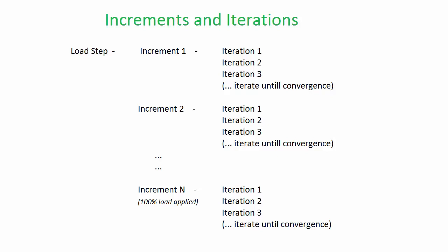However, in a nonlinear analysis, it is almost always better to set smaller increments. This is because the solver is unlikely to converge to the solution when it applies the entire load in one increment, and will internally do a cutback and try to solve with smaller increment size. For highly nonlinear problems, Abaqus Standard might have to reduce the increment size repeatedly. This wastes computational time. Hence, it is preferable to have multiple increments from the beginning in any nonlinear problem.